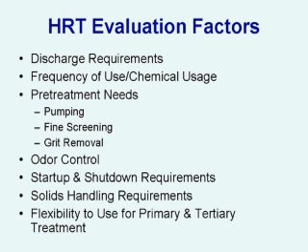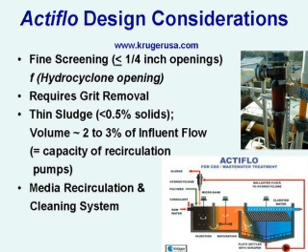As the city was evaluating the use of high rate treatment, there was a question of what technology to use for the ballasted flocculation, and the various evaluation factors that were looked at included those shown on the screen. The discharge requirements clearly needed to be met, and a side-by-side pilot study was done of ActiFlo and DensaDeg technologies. The city has chemical usage that is unique to their flow stream, as is true at most treatment plants, and the chemical dosage was evaluated as part of the planning for the facility.